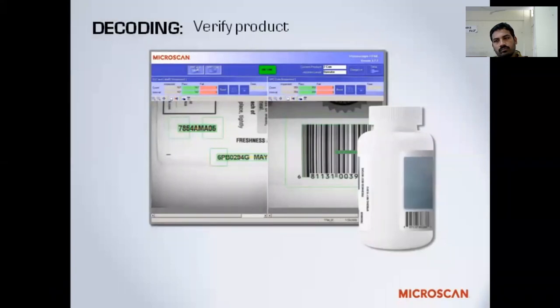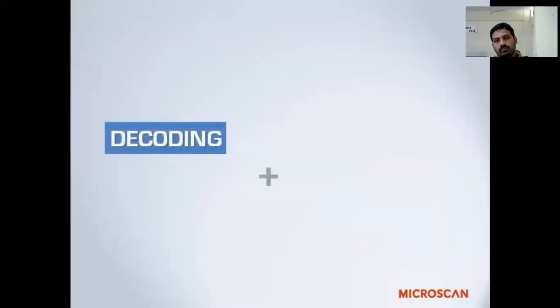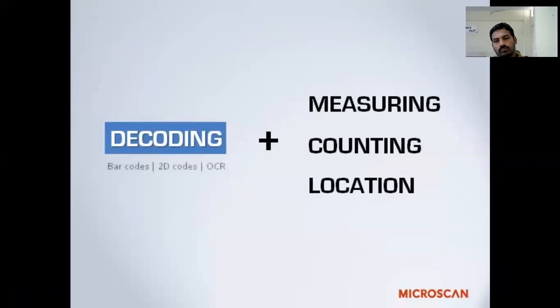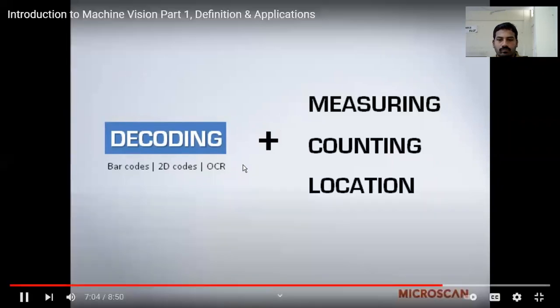An obvious question here is, why use machine vision to do this when dedicated auto ID systems would do the same thing? You might think of machine vision as auto ID or barcode reading plus. The plus is the ability to run other measurements and operations in combination with the reading of barcodes or text. For example, you might want to read a label and also check that it's properly aligned to the product. In other cases, you may need the ability of a machine vision system to tackle tougher applications that require more capability in terms of image pre-processing, or in the case of a PC-based system, sheer speed and processing power.